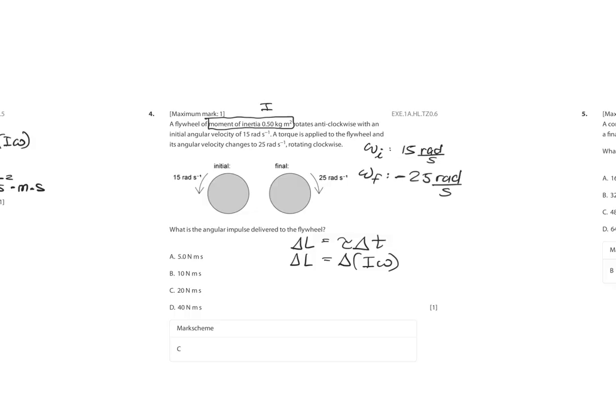And it wants to know what is the angular impulse. So the impulse equation is either torque times change in time, that's kind of like J equals F net t, or the sum of the forces times the time, or delta moment of inertia times omega, which is the analog. Let me write down the analog. The analog would be J equals m delta v, or delta mv. The mass is not changing, just as the moment of inertia of this disk is not changing, but the angular velocity is. And so the change in momentum is the impulse here.